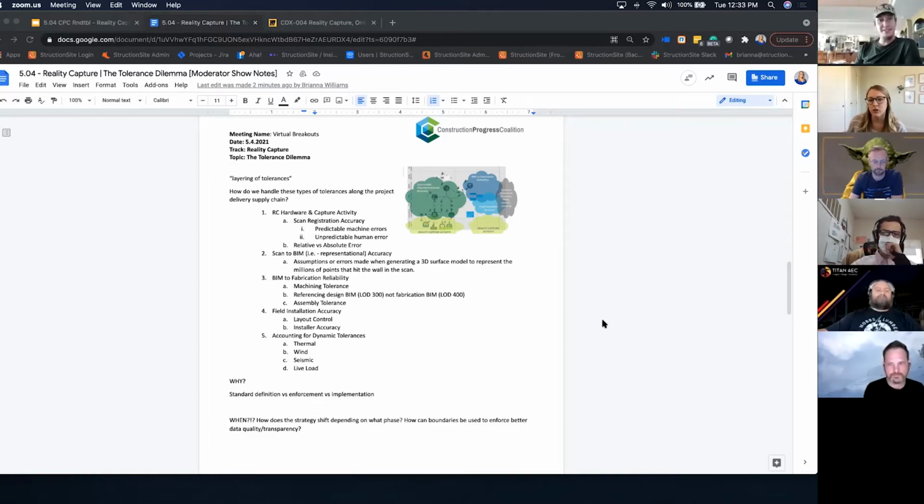Yeah. So think about whether you're comparing apples to apples or apples to oranges, because the range error and the point accuracy may be telling you different things. I'll give a specific example, and I will admit I'm biased on this, but the parent company for ClearEdge, Topcon, likes to provide point accuracy because they feel it gives you the complete understanding, but point accuracy is always worse than any individual one accuracy.